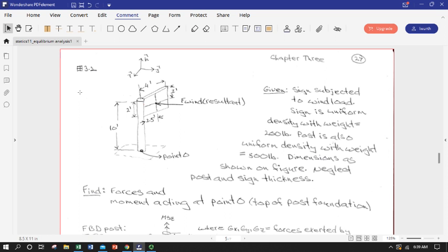In the previous lecture, we basically defined the role of the free body diagram and the equations of equilibrium. The sum of the moments in all three orthogonal directions and the sum of the forces in all three orthogonal directions have to be zero for something to stay in static equilibrium, which is the condition that we are accepting here in engineering statics. That would be equal to ma if we were in dynamics and allowing acceleration, which we don't want. So that simplifies our equations and makes them easier to solve.